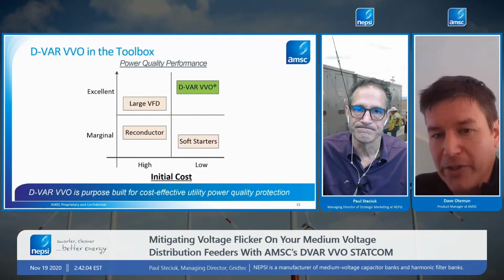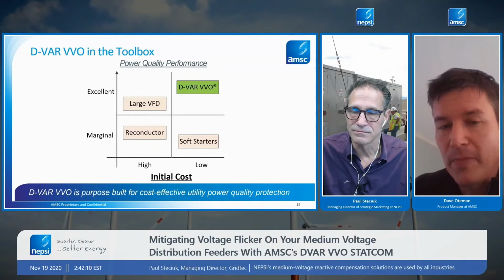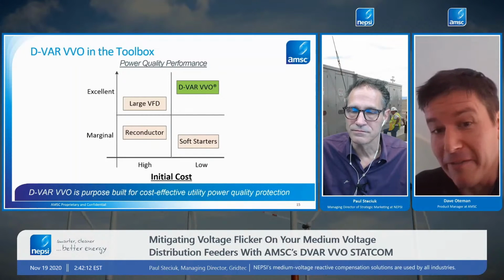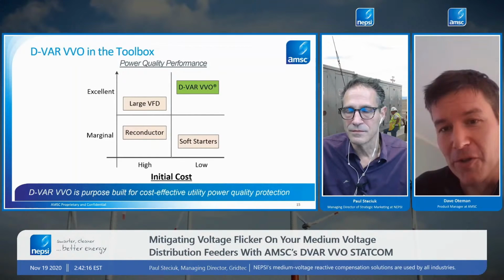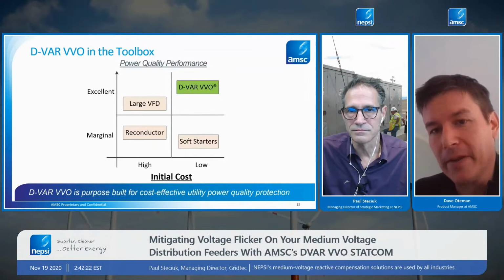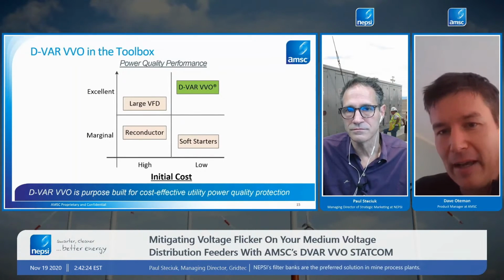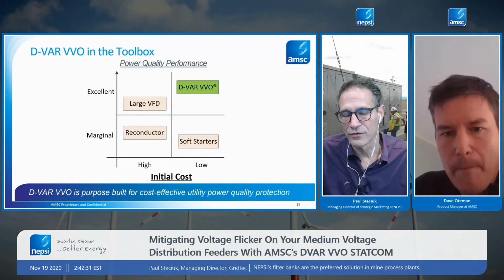And then the other thing is STATCOM can also be programmed to address all power quality problems on the feeder. So depending on how we configure the control mode, that STATCOM can address not only motor starting issues, but other issues being caused by other devices at a plant, for example. Yeah, there's ongoing costs too for those load level solutions.